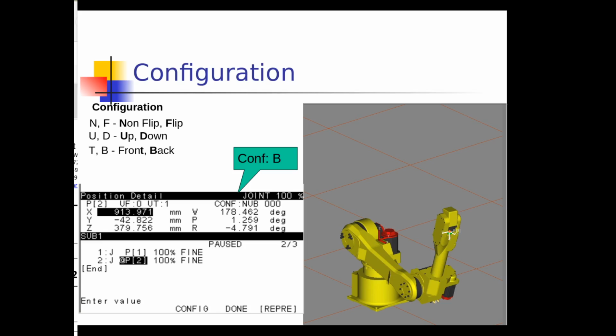So this configuration here, when you store a point as a Cartesian point with XYZ, yaw, pitch, and roll, you store the user frame. You see UF there means user frame, and then UT means tool frame. Okay, it actually almost looks like a V, but it's supposed to be a U there. It's just the font they're using.